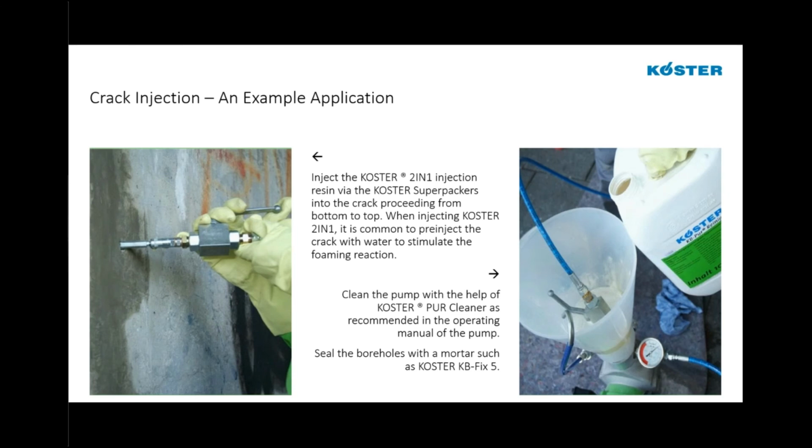We're going to get into more of the details and FAQs of the injection a little bit later, but for right now, we'll assume that the injection has been done. The injection is completed. Again, with the 2-in-1, we inject for that foaming reaction. We wait about 15 minutes. We go back and post-inject. We re-inject that same material into the same ports for that solid body resin to form and encapsulate the foam and give us that longer lasting elastic solid body performance.